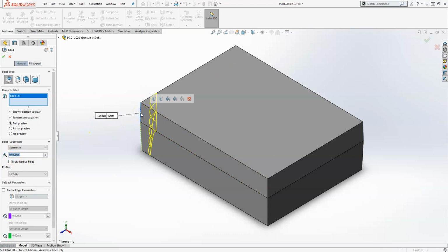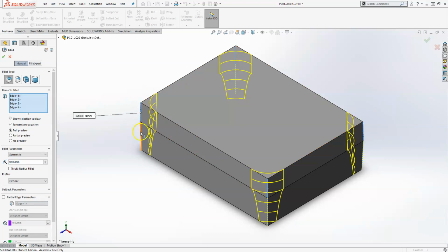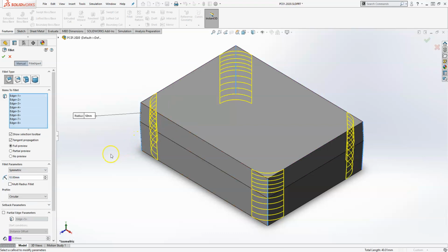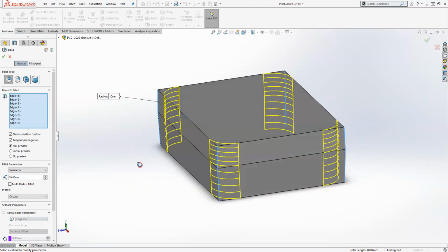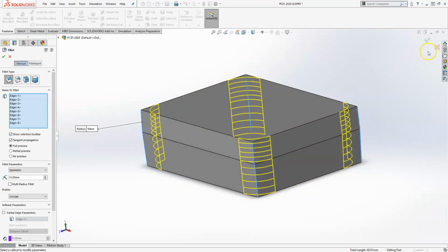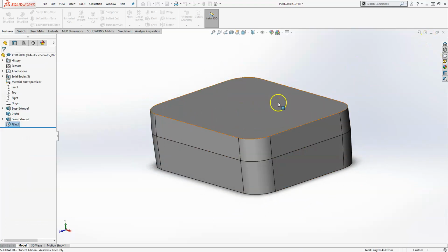So if I click on that corner and then I come up here, you'll notice that when I select this one, it chooses all the same corners of that same rectangle. So I'll select that. And if I choose this bottom one, I can select that. So instead of selecting 8 different corners or edges, I can select 2 and use that menu to get it.